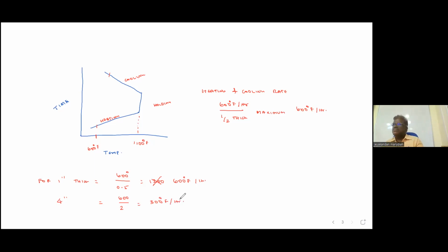This understanding is important. Now, from the exam point of view, they will ask what should be the holding time. So 1 inch per hour is the rule, minimum 15 minutes. But when the thickness is more than 2 inch, we will add only 15 minutes. The table is actually very important for the exam. Just write this, then we'll.